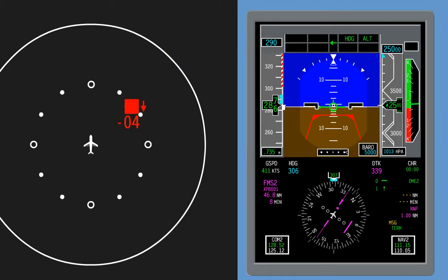When the TCAS detects an RA condition where certain ranges of vertical speed are not recommended, preventive RA, one red trapezoidal avoidance zone is displayed. When the TCAS detects an RA condition and a maneuver is recommended to increase the vertical separation, corrective RA, Descend. Descend. One or two red trapezoidal avoidance zones and a green rectangular fly-to zone are displayed.